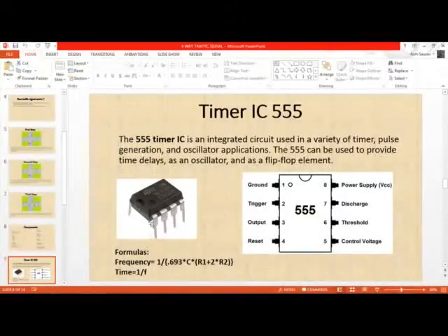Pin number one, where we will start counting from the left side. 1 2 3 4, these numbers are denoted here. Pin one is for ground, and two we'll be shorting with the trigger and threshold, as you will see on the next step.